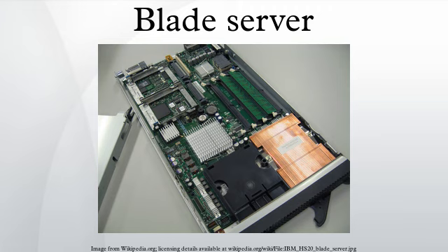The PCI Industrial Computer Manufacturers Group, PICMG, developed a chassis blade structure for the then emerging Peripheral Component Interconnect bus, PCI, which is called CompactPCI. Common among these chassis-based computers was the fact that the entire chassis was a single system. While a chassis might include multiple computing elements to provide the desired level of performance and redundancy, there was always one board in charge, one master board coordinating the operation of the entire system.